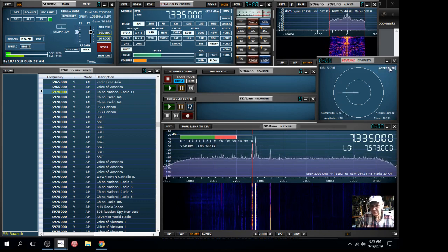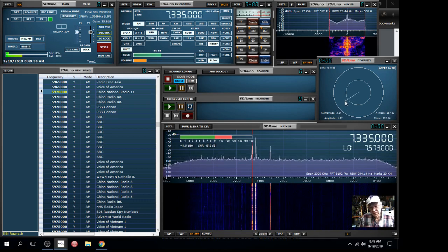Now you can turn this off. You click this, and now you can manually, by clicking your mouse on that little bar pointer, tune it and watch the signal to noise ratios. It was down in this area here, and of course it's changing. You can see as I tune away from the point that it had selected, the numbers get worse. So let's go back to auto, and notice it'll jump back down in this corner,